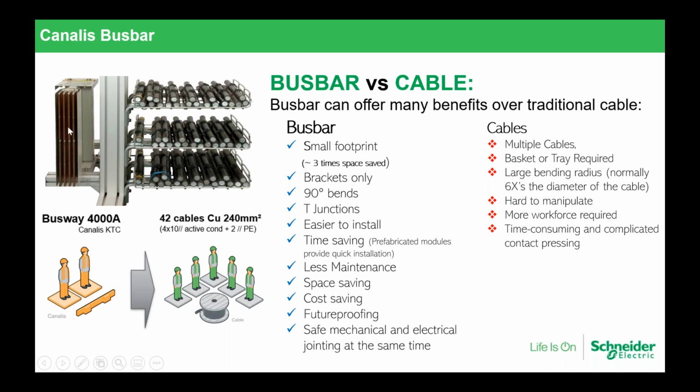If you can use the Busbar, you reduce the surface needed for the electrical distribution a lot. So just imagine the reduction of the space you need by using the Busbar instead of cables for higher ratings, but not only.